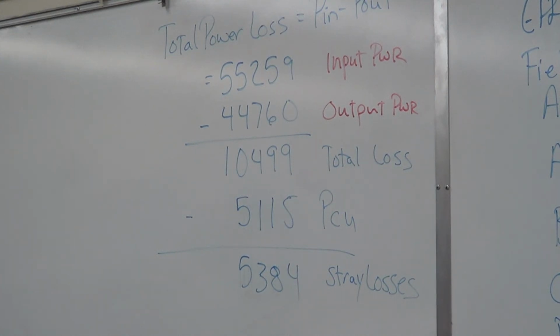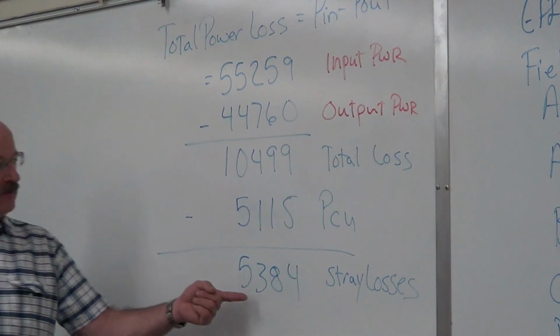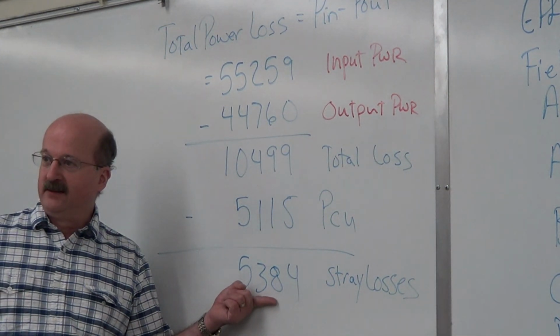Questions? Now, they're calculating this when they're setting up a system. When the system's running, are you having to go back and redo these calculations at some point? Like, trying to get an idea of how it's going to be used in the real world. If you know what your copper losses and your stray losses are, and the bearings start going out, your stray losses are going to start going up.